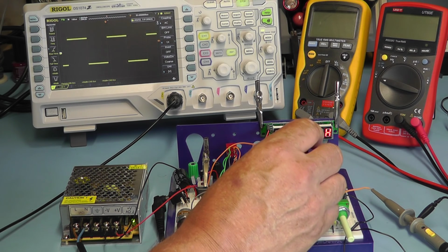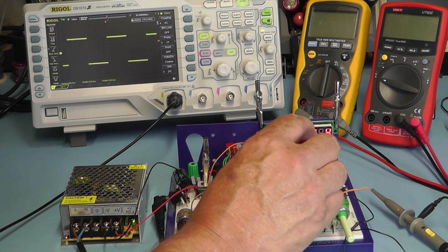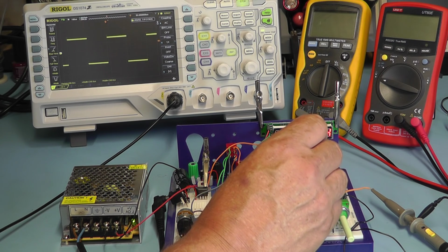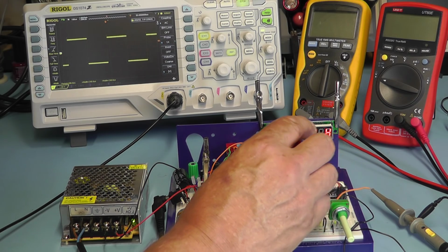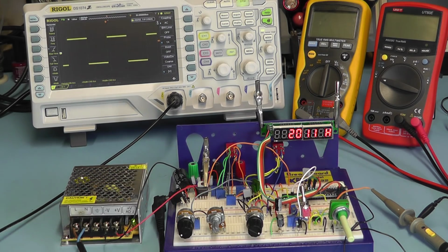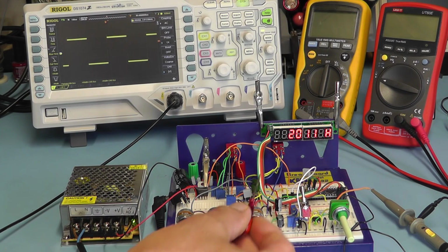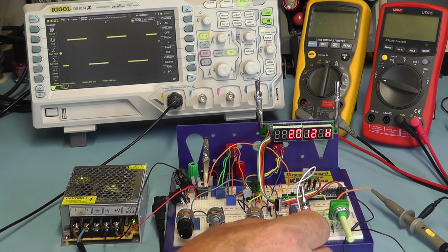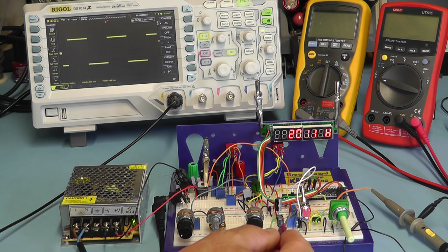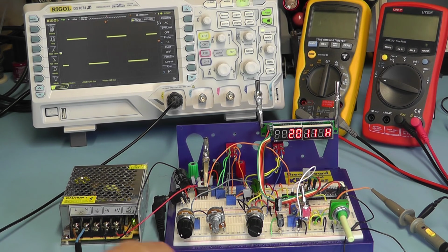what I'm finding here is I'm not able to alter the amplitude very much of that, and I suspect it's due to the DC level voltage input from the square wave going into the op amp there. So what I'm going to do is isolate that from the previous stage by using a small capacitor. I'll try a 0.22 microfarad. So let's see if that works.